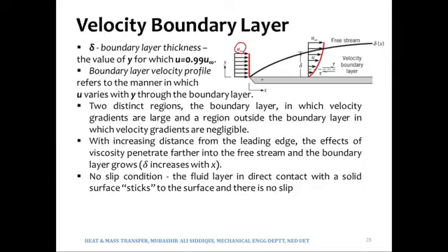So the boundary layer will start originating only from the point where the plate starts. Right? And then we will have this velocity profile where the velocity will keep on increasing from 0 to the value of u infinity ultimately. There is also shear stress being shown. Of course, you know that between the two layers of fluids there would be shear stress, and this is being shown over here. However, we will refer to the expression of shear stress in chapter number 6.